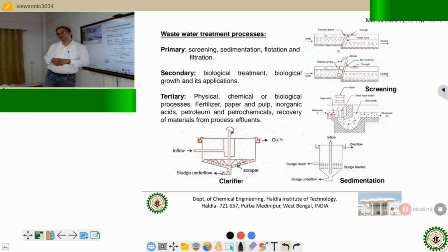Most of the cases in wastewater we use some bacteria, so that the bacteria decompose the organic component. Okay. In most petrochemical and oil industries, oil leakage is there, and it comes directly to the water, and the separation of that water and oil is very difficult. If the oil level is very low, it cannot be detected or separated efficiently. Rather, we should go for biological treatment.